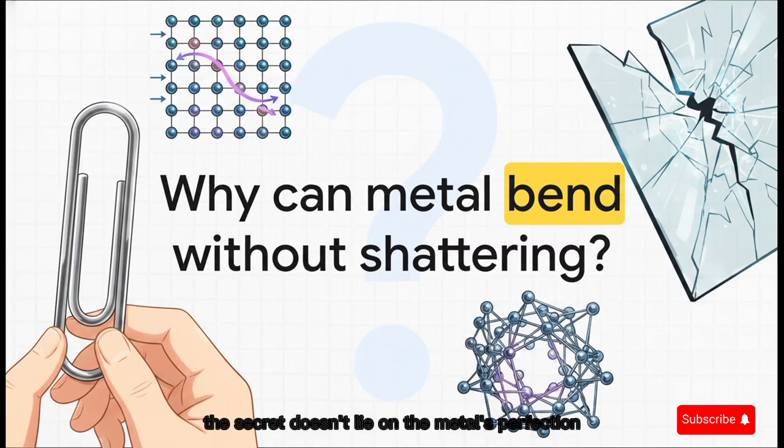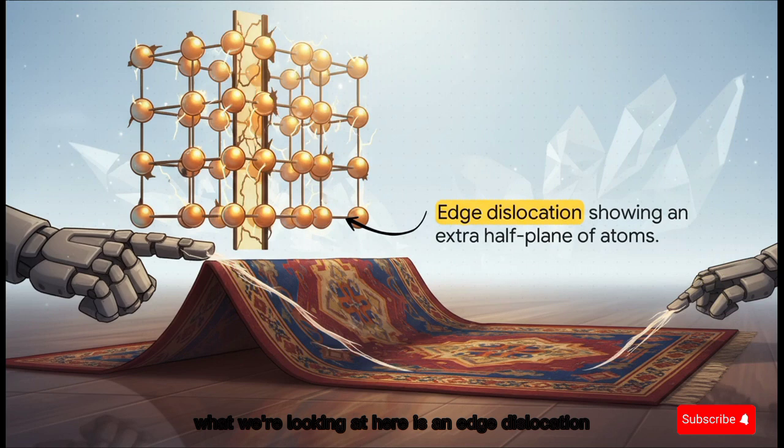The secret doesn't lie in the metal's perfection, but in its microscopic, one-dimensional misalignments. We call these dislocations. What we're looking at here is an edge dislocation. Notice that extra half plane of atoms squeezed right into the crystal grid.